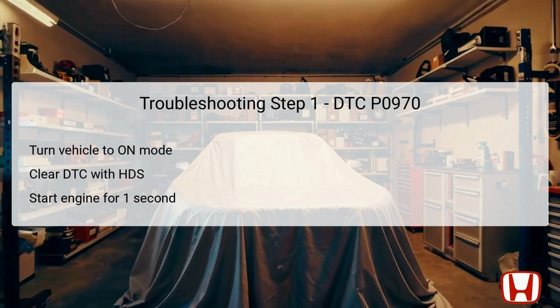If DTC P0970 resurfaces, the failure is confirmed, moving you forward in the troubleshooting process. If it does not appear, it could signify an intermittent failure where you should check for loose connections and terminals.